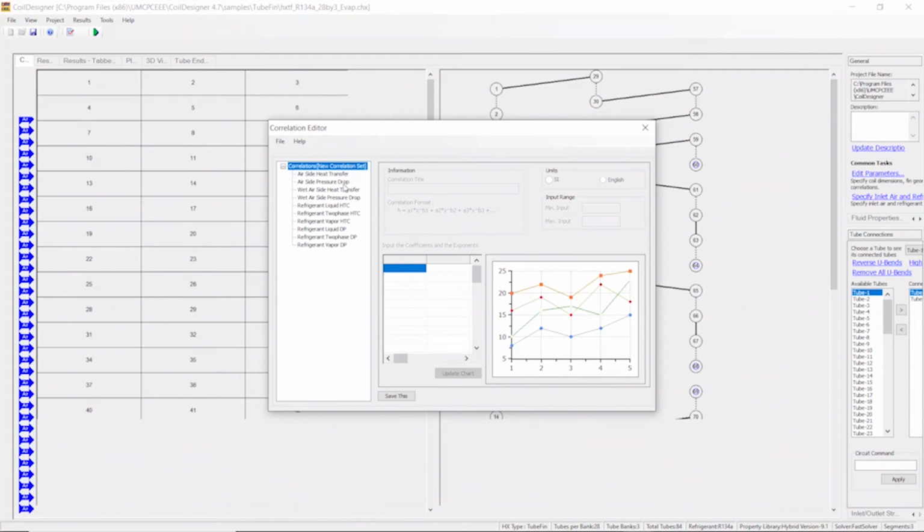To create a correlation, select the type of correlation you would like to create and right-click or control-click. Then press Add. If done correctly, this should produce a small box with a plus in it to the left of your correlation category. Press on the box, then select the new correlation with a number attached to it. This is where you will create your custom correlation.